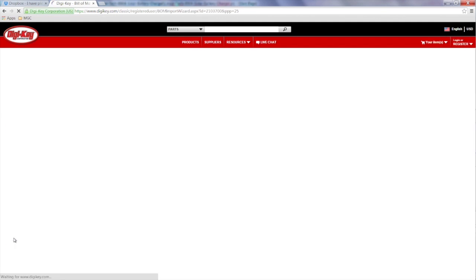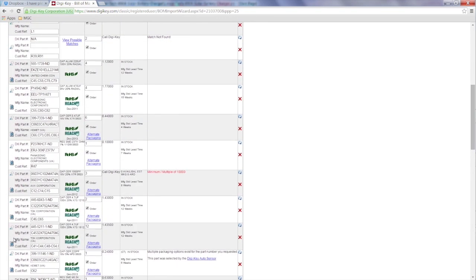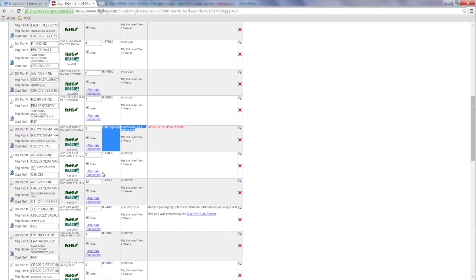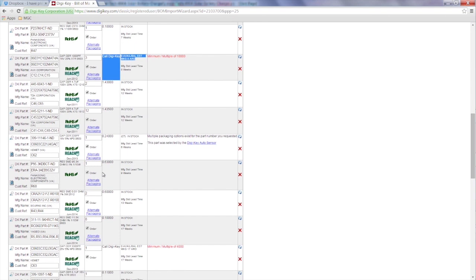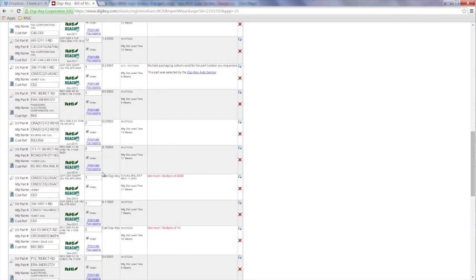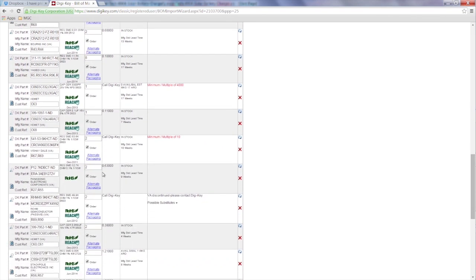By uploading the design BOM to Digi-Key, we can see there are a few parts that are not in stock or marked for obsolescence. Digi-Key does a very good job warning you off of parts that they know are not good picks for new designs. Digi-Key also provides a list of alternate parts when they detect appropriate matches.